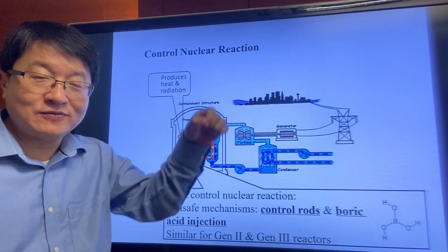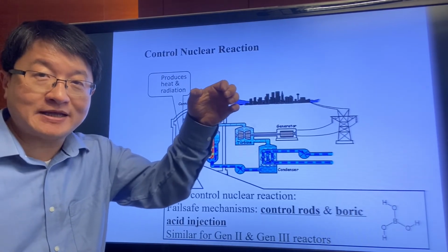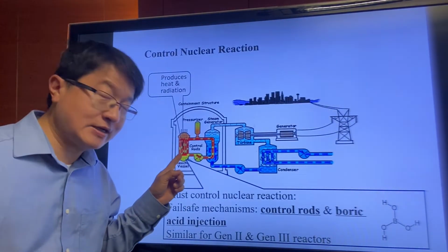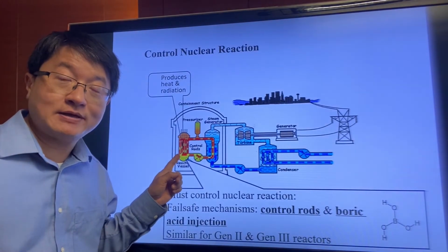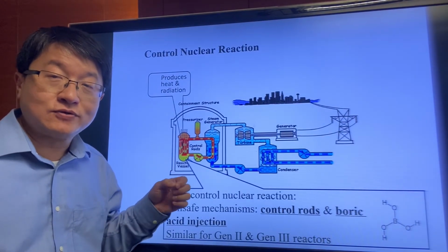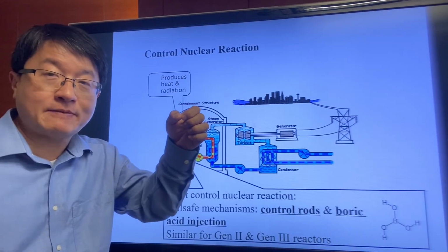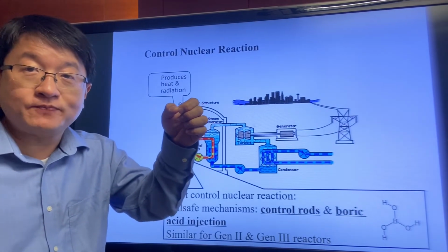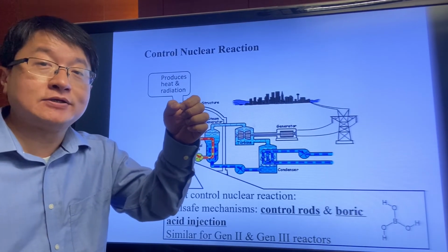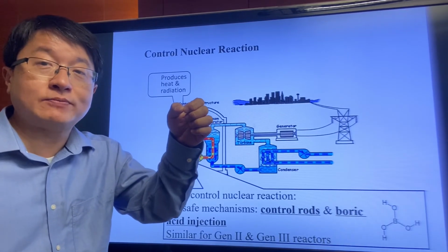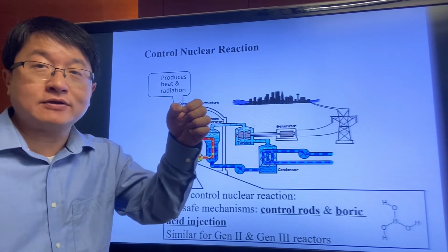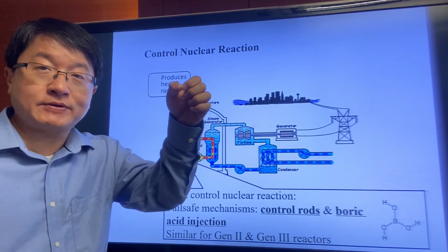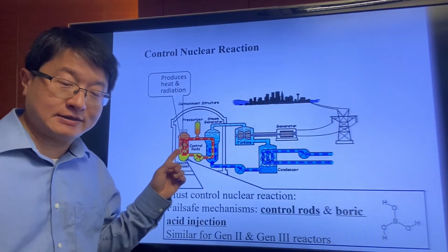Gravity. Okay? When we release a cam, then this control rod can drop into the reactor, and this is the most reliable. And we can make use of an electromagnet to hold the control rod and apply a current to hold it, and when there is an emergency, this current will be terminated. The circuit will be open, or the power supply to hold this rod will stop. Then the control rod can be released and dropped into the reactor.